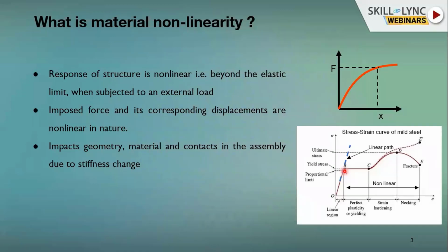Then further, if we just stretch the material, it will further get into the plastic deformation zone, a permanent deformation zone. So anything beyond point A is going to be the nonlinear part beyond plastic deformation. Then obviously it goes up to the necking, which is D, and of course where you hit the ultimate tensile stress, and post necking is where the fracture happens. Now, it can have temperature effects too. When temperature gets into the picture, the phenomenon of creep will dominate. We're going to talk about those terminologies in the following slides.